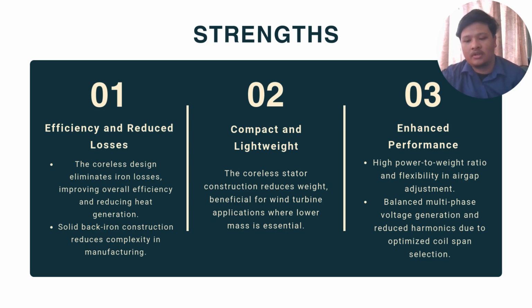Let's start with the strengths of this design. First, efficiency and reduced losses. The coreless design eliminates iron losses, which significantly improves the machine's overall efficiency and reduces heat generation. Additionally, the solid back iron construction simplifies manufacturing, making it less complex compared to other designs.